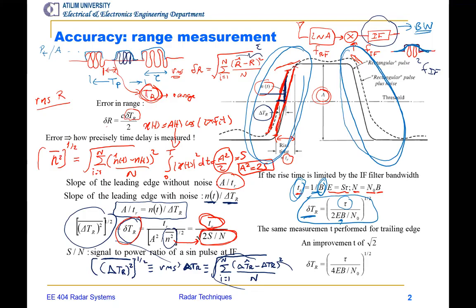So together, that's going to be an averaging operation. Let's say this is the leading edge, and we have a trailing edge here, and then taking the average and its square root will give us a factor of 1/√2. So we simply reduce the RMS error by using the errors we measure for the leading edge as well as the trailing edge.